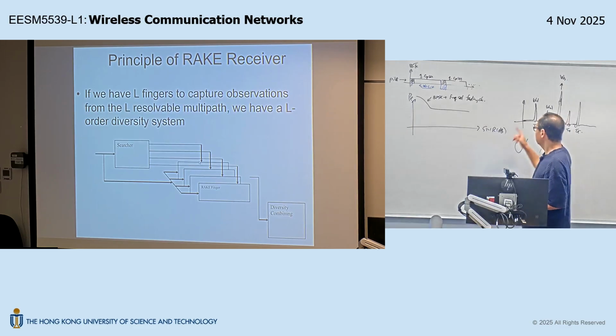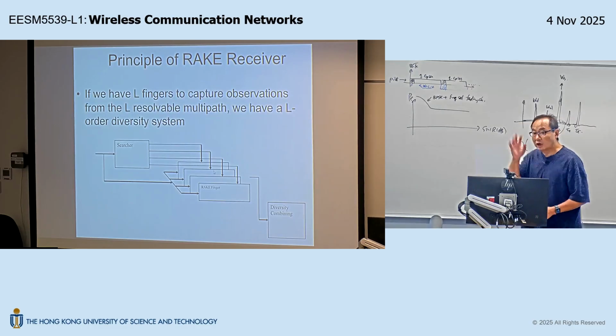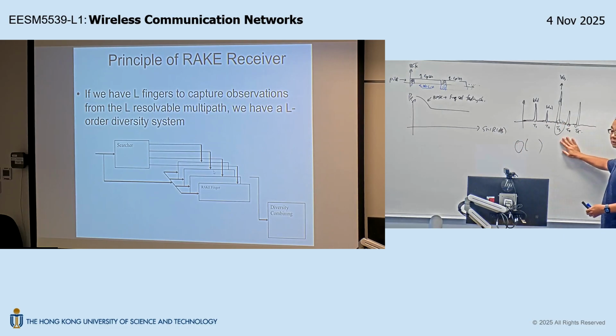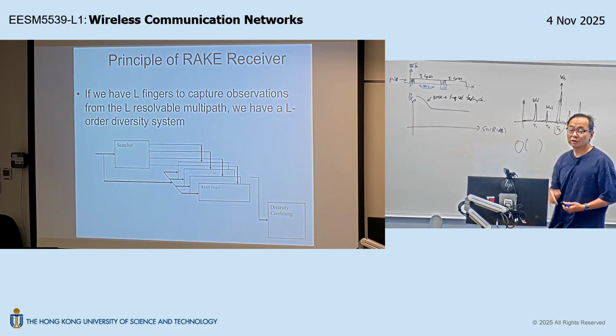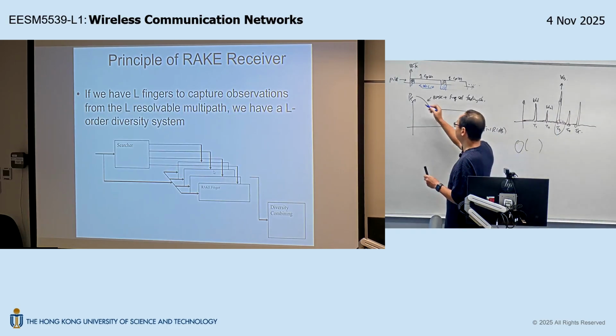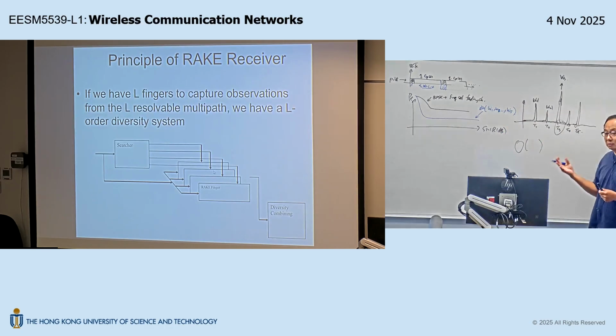And now, if you have 5 despreaders in the rake receiver, you can despread over these 5 despreading timings. So you can have W1 up to W5. Then you do diversity combining, you do MRC combining on these 5 diversity measurements. Then let's say your error probability curve becomes something like this. So this will be diversity combining with W1, W2, up to W5. That would be something you would obtain with 5 despreading fingers in your hardware.